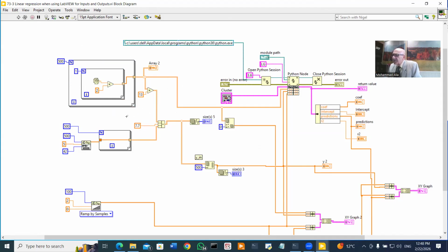By using LabVIEW, they were programmed in order to acquire the data from the real processes, and after working out the necessary algorithms there, and in that time the most important were the control algorithms, and after manipulating this data with the necessary algorithms, the output is generated also to the ports of the data acquisition boards or specific boards like NI myRIO, for example, so that it will feed the real process.